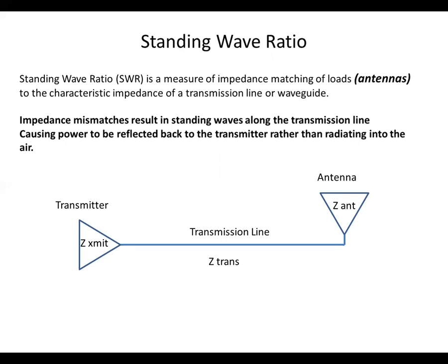And then there are devices, antenna tuners, that can be connected between the transmitter and the feed line to match the impedances so that reflected energy doesn't get back in and hurt your transmitter. Now, a lot of times, you'll put an automatic antenna tuner here, and a lot of newer radios have internal antenna tuners that will do the tuning for you. And you can get a good match between your transmitter and the input of the antenna tuner.